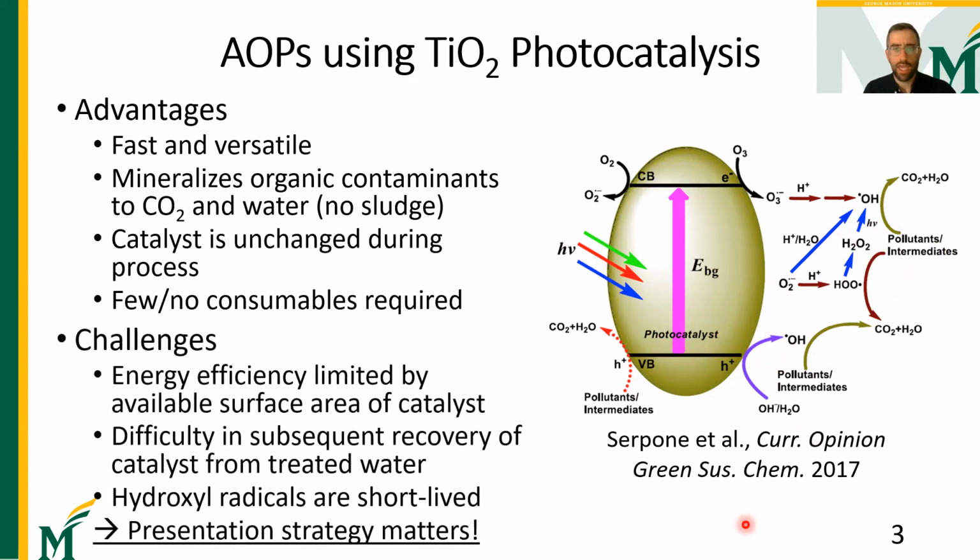However, heterogeneous AOPs have a number of challenges that have prevented their implementation in broader water treatment systems. Most notably, the kinetics and thus the energy efficiency are limited by the available surface area of the photocatalyst. And generally, it's difficult to recover these photocatalyst particles from the treated water. Also, the hydroxyl radicals have a very short lifetime. And all of this means that the presentation strategy matters a lot. And for this reason, to maximize the specific surface area, the catalyst is generally presented in nanoparticulate form.